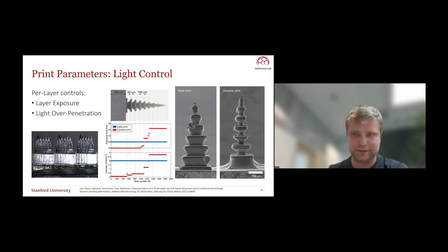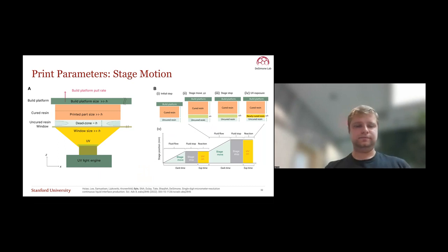So this is another slide showing light over penetration and utilizing what we call dynamic print controls, where the light exposure is adjusted for each individual layer to prevent this Z overcure from occurring. The other aspect of this is stage motion.